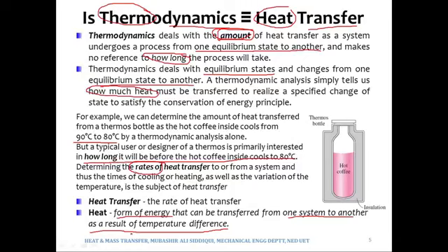This energy traffic will keep on going till both bodies attain the same temperature. Let's say both bodies attain 50 degrees Celsius, then this energy transfer will no more exist. The energy which was being transferred from A to B, from the higher temperature body to the lower temperature body, was mainly because of that temperature difference. When that temperature difference did not exist, the energy transfer did not take place. The energy being transferred due to temperature difference is what we call heat.